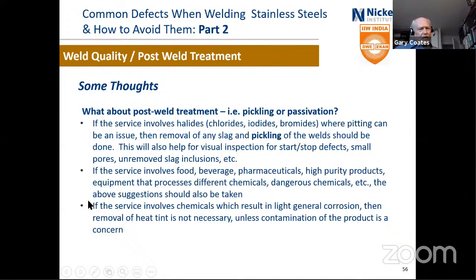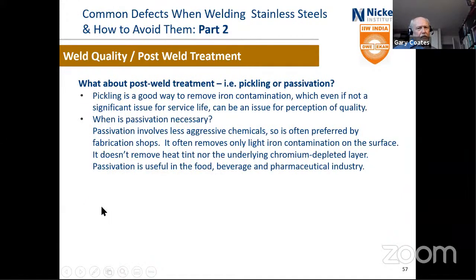And if the service involves chemicals which result in light general corrosion, often a little bit of heat tint is not removed. And finally, pickling is a good way to remove iron contamination. It removes the heat tint.